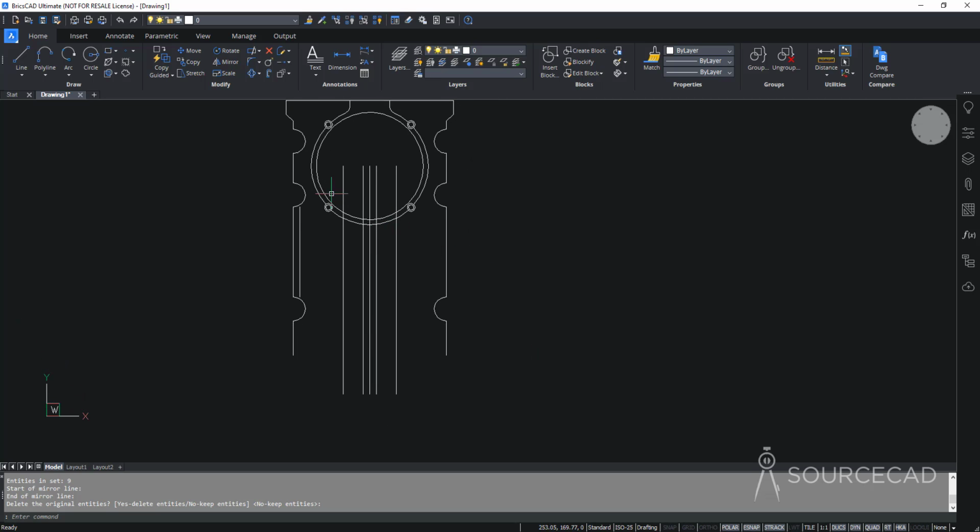Now with that mirror image, we are ready to create our horizontal line. So I'll go to the line tool, I'll click on the center of this arc, and then the center of this arc to make our horizontal line. Now these are all mostly construction lines which we'll later delete, but for now we just need them for creating the exact geometries that we need. So the next thing will be offset once again. So I'll go to offset, and this offset distance is 13.87.